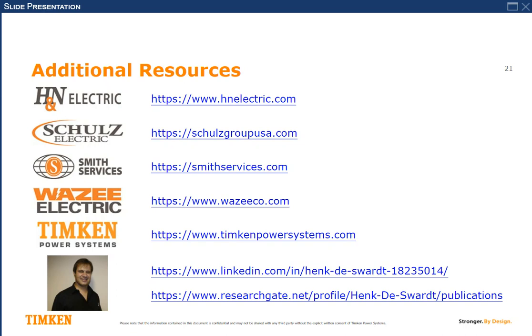Practically, I've heard of companies that said after 10 rewinds, we should throw it away. 10 rewinds should be a life of 10 times 8, 80 years. So how many plants last 80 years? It's difficult. It's more important to say, when we repair the machine, let's make sure our repair company gives us really good reports. Before I start the rewind, say, give me that core test report so that I can actually see what the numbers are, things like that.